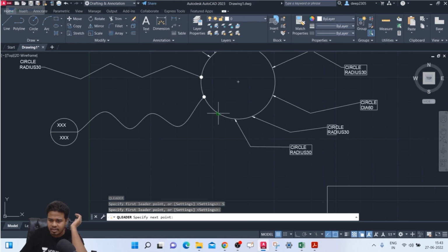Now left click here. So see, say this is 0 degree, this is 30 degree, meaning it will snap at every 30 degrees. See the angles, it will track the first segment.